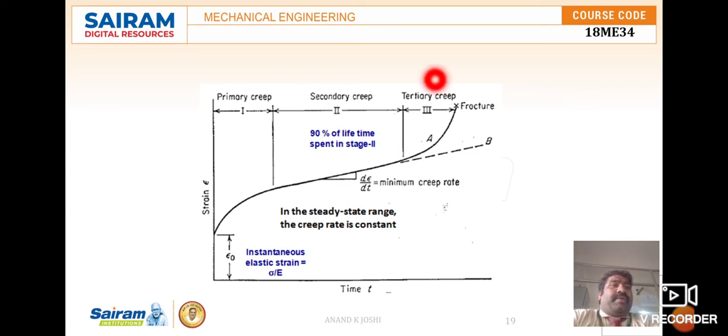In tertiary creep, the material is almost reaching the final stage of creep. This is the third stage of creep, in which the creep rate accelerates until fracture occurs. Tertiary creep occurs when there is a reduction in cross sectional area due to necking, or an effective reduction in area of the specimen due to internal void formation. Further, this necking causes an increase in the local stress of the component, which further accelerates the strain, and eventually the ductile material will pull apart, fracturing around the defects in the solid material.